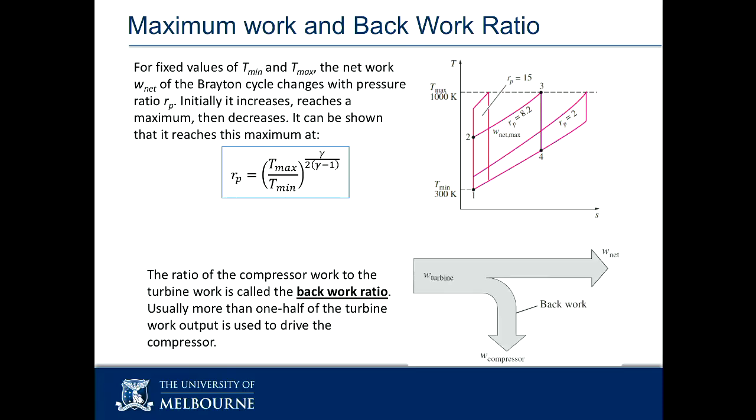There's one last concept that we give a name to. The turbine drives the compressor. So they're connected on a shaft in the machine. If it's a gas turbine that's powering a generator to make electricity, there's work that goes out to that generator to make the electricity, just in the shaft, but also the turbine is powering the compressor. So the work that went into the compressor, the only place it came from was stuff that the turbine was doing, and anything you've got left over is what gets useful work, net work out of the system.